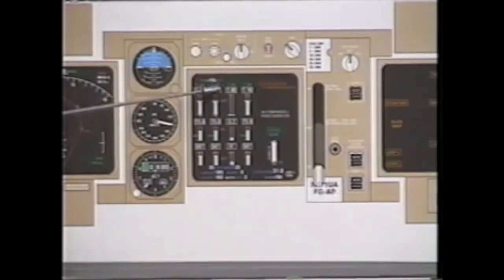Thrust mode enunciation, in this particular case, go around or GA, is enunciated with the limiting EPR of 1.50. Various thrust modes we can encounter here are TO for max EPR, D-TO for reduced EPR, climb, climb 1, climb 2, continuous, cruise, go around. All of those are different thrust modes with the appropriate limit EPR displayed in green.